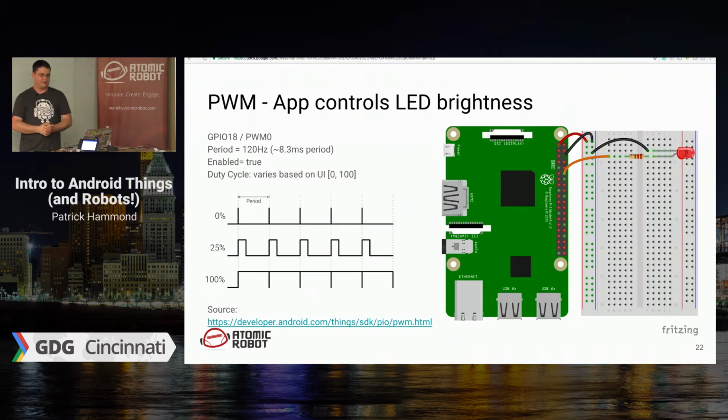Okay, so next thing, we've got another LED down here. We're going to control the brightness of it. So what we use for this, and if we go back to the screen before, we talked about this pulse width modulation. The way I like to think about that one is, right now the lights in the ceiling are on. If I turned them off, the room would go dark. Now imagine my fingers being able to do this really quickly. If I did it quick enough, I could kind of make the room look dim. And this is kind of how we're going to do it.